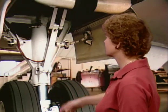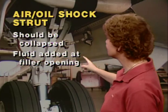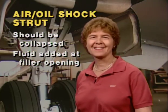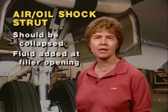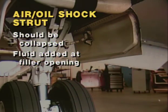By the way, if you're going to service an air oil shock strut, the correct way to do it is first you want to collapse the strut and then add fluid up to the filler opening, install the air valve core, and then inflate the strut. You do not want the strut partially or fully extended because you won't get the oil at the right level if you do that.